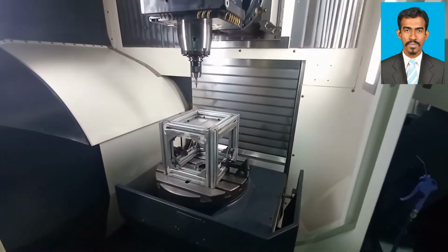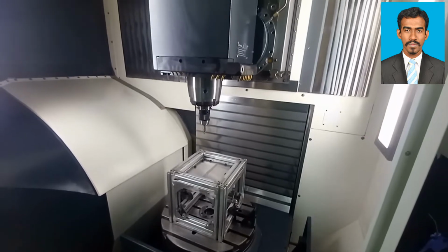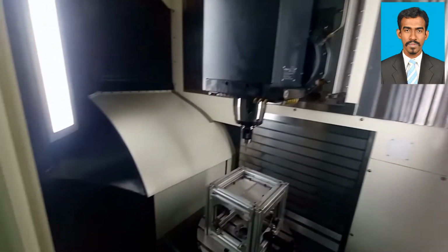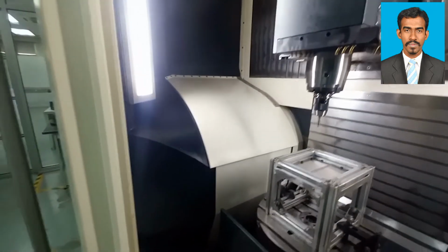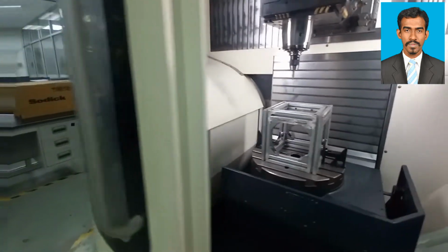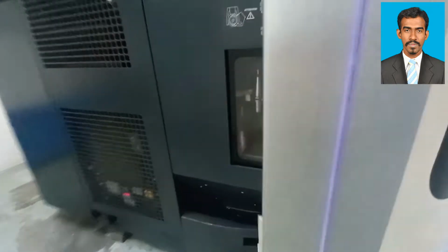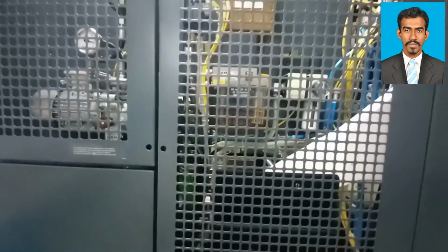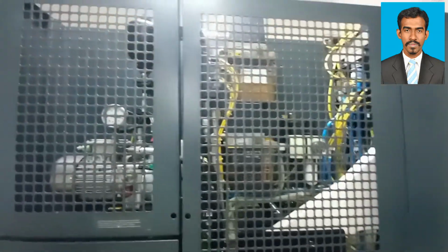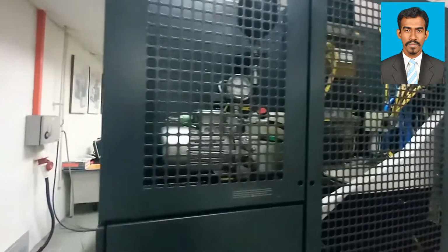A 5-axis machine allows you to work on every surface apart from the clamping area and the bottom. When working on contoured parts that require machining on several faces, you need several setups on a 3-axis machine if you are rotating manually. But in the case of a 5-axis CNC machine, it completes the job in a single setup, reducing the number of setups and helping you save time.